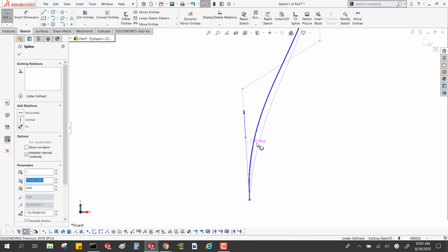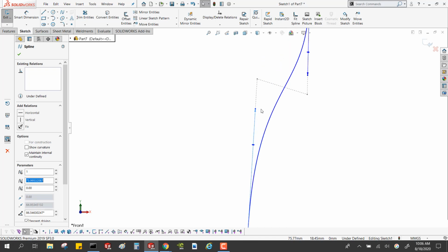The diamond shape just controls the angle that we're going to be going from. The arrow controls the magnitude of tangency, so how far off of this edge is it going to be going in this direction of this dashed line. And then the third one at the point actually controls both of them, the magnitude and the direction of tangency.